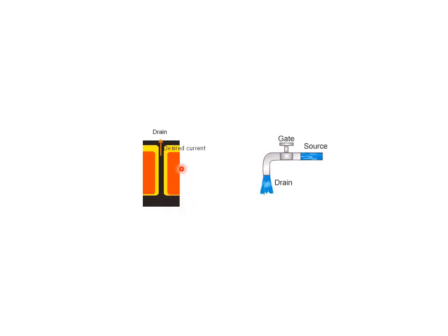Theoretically, how does this transistor operate, as in any BJT, between P-type and N-type semiconductor? If you remember when we talked about the p-n junction diode, we said what happened when you put a P-type and an N-type semiconductor joined together. Remember there are two effects that happen: the depletion layer and the barrier potential. What causes the depletion layer and the barrier potential? Basically, the recombination between free electrons and holes.